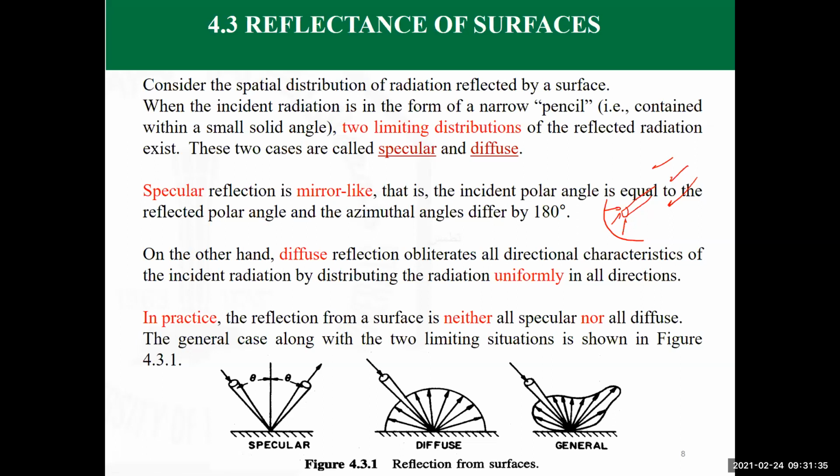Doctor, can we make use of this heat from the plates? It depends on your design of the system. The latest design that has been released of the PV panels, which are the panels that are converting the solar energy into electricity, photovoltaic, has a major problem: the PV panels' efficiency gets lower with temperature. So we're talking about two conflicting things.